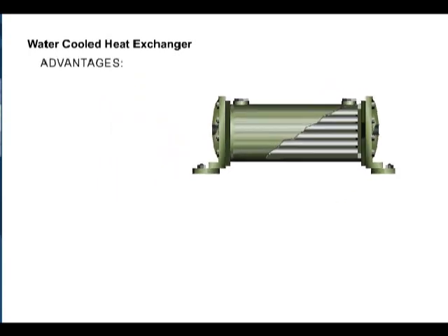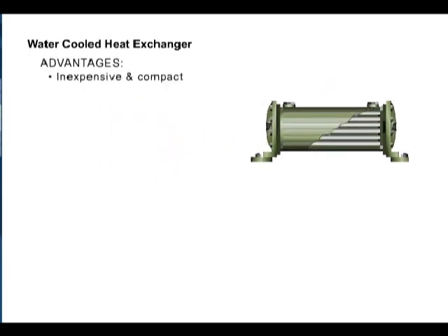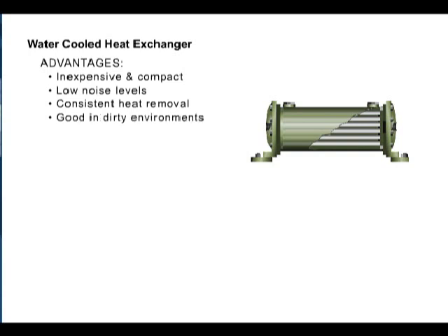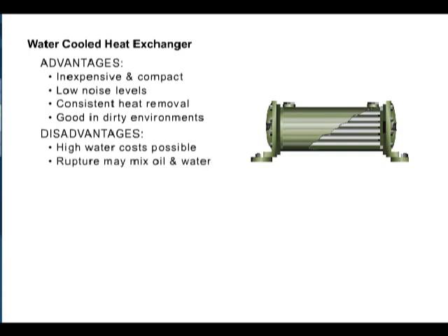There are advantages to this type of cooler. They are the least expensive, they are very compact, they do not make noise, they provide consistent heat removal year-round, and they are good in dirty environments. The disadvantages are water costs can be expensive. With rupture, oil and water may mix, and they usually require regular maintenance from mineral buildup.